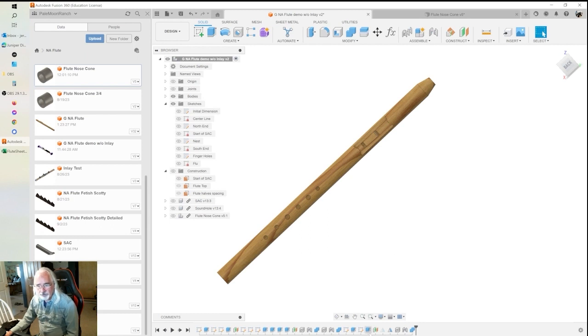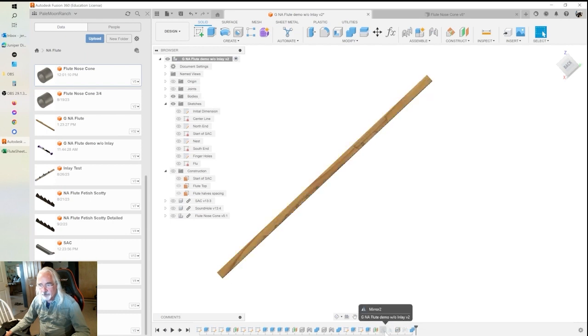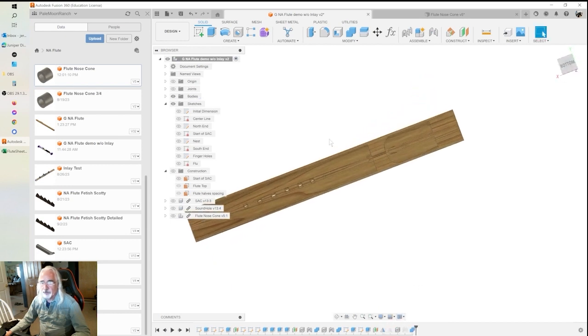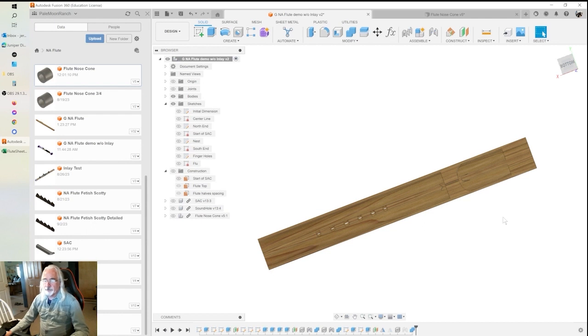So I'm going to back up to that plane that we defined and explain that this plane will determine. First, I'm going to unsuppress. I'm going to turn that off, and I'm going to turn on this mirror, which puts two of them side by side. Now, if I've used a single piece of stock and cut it down the middle and folded them apart, I'm going to do it this way, where I'm going to put these two pieces together on the CNC, butt it up tight to each other, and let it carve out this inside just as it looks there on your screen.